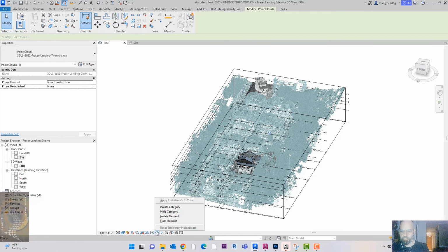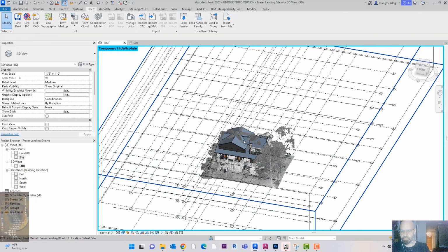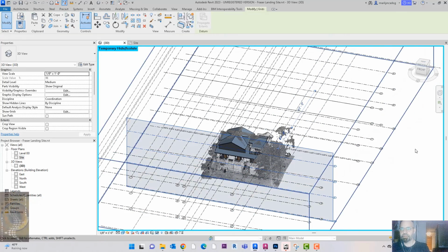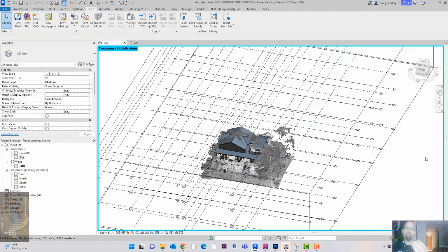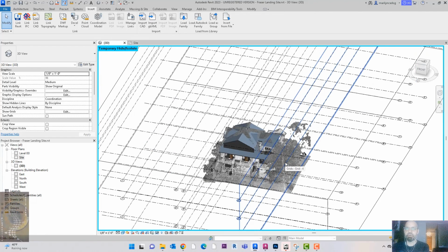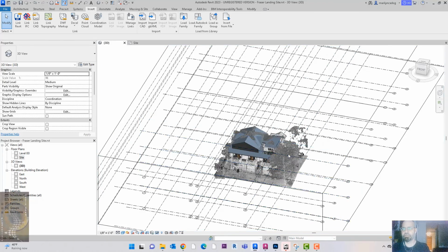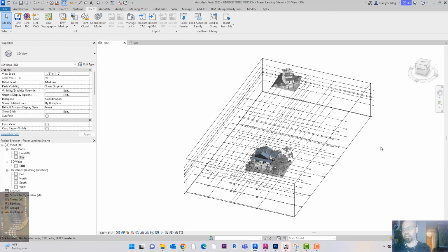So then what you will do is I am creating a Revit file for every building in here. So I have like 11 buildings, so I'm going to have 11 Revit files. So I create a site file, I use shared coordinates, and then I link those in there.